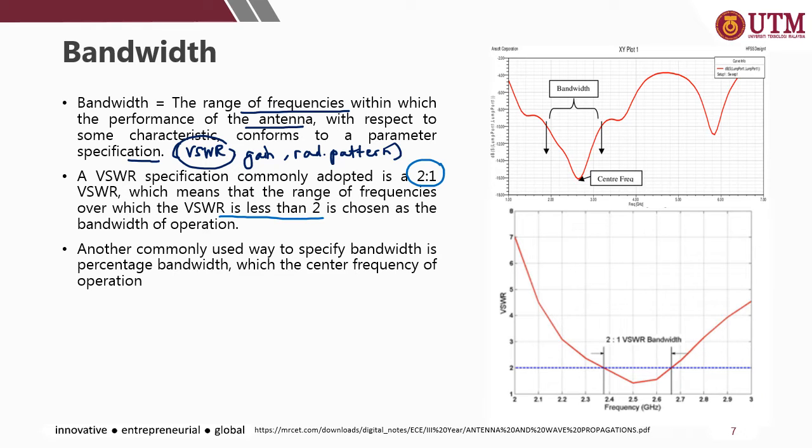So for example, we can measure the bandwidth by referring to the return loss or S11 graph, and also the VSWR graph.